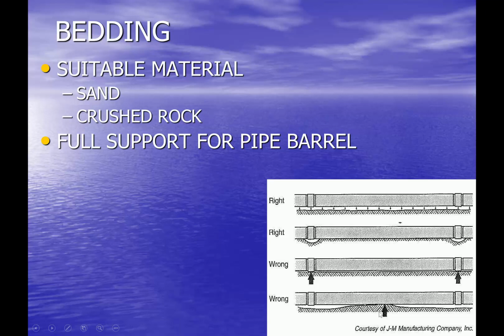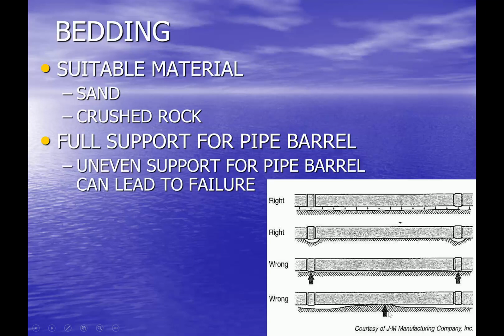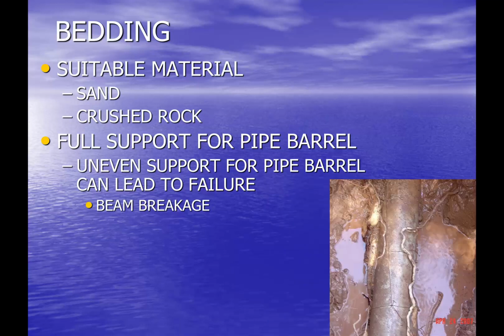Well, with all of the surface loads, even the weight of the backfill, plus the loads from the street pushing down on the pipe, you're going to create stress right along the top of the pipe above where that high point is. And ultimately, that uneven support can lead to those beam breakages that we've talked about in the past. So it's important to completely support that pipe.